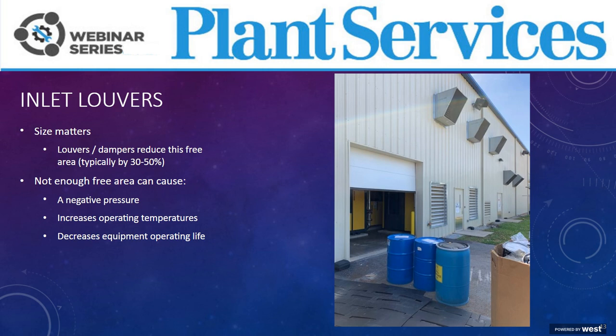Here we see a general compressor room from the outside. So free area is what we want to focus on here. Free area is actually the unrestricted area of an opening. You want to take this into account when sizing openings in a wall.